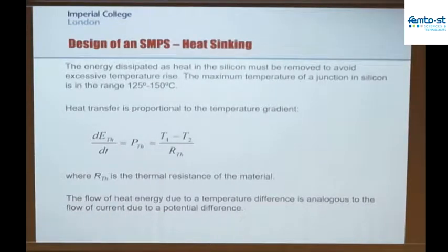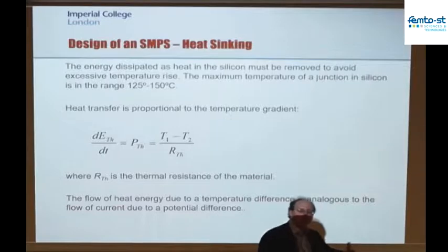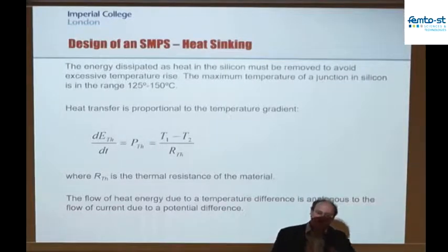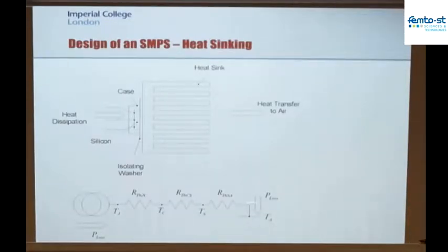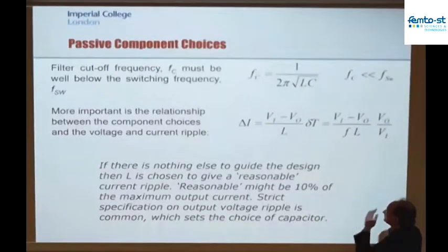Heat sinking, I'll probably skip that because actually, as I keep saying, it's not really very relevant from the perspective of an energy harvesting device. If you do want to design a piece of power electronics with a heat sink, then the design flow is fairly straightforward. You work out the total losses in the system, and then you build a thermal model from the transistor all the way through to the ambient and figure out what the thermal resistance of the heatsink needs to be in order to keep the transistor at the right operating temperature. And you can do that with a thermal equivalent circuit. It's a very straightforward calculation. If you ever want to do that, like I say, you can look that up. It's fairly straightforward.